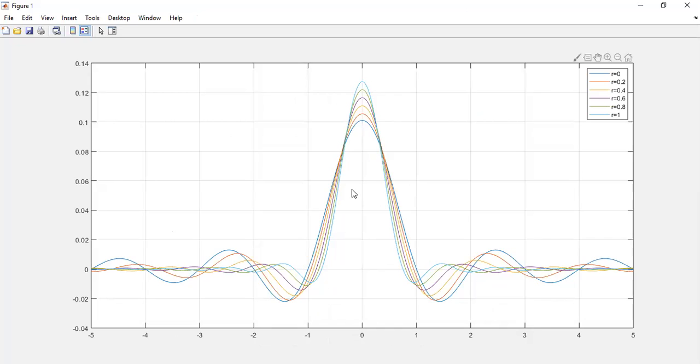And what we can see is that for different versions of this raised cosine, that is, the different roll off factors, the wave kind of shifts in such a fashion that the data is not essentially zero at integral multiples of the time period. You can see that it is not essentially zero at those time periods. It is going anywhere that it wants, right?